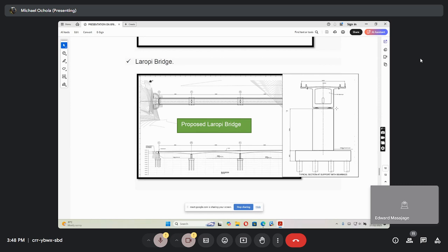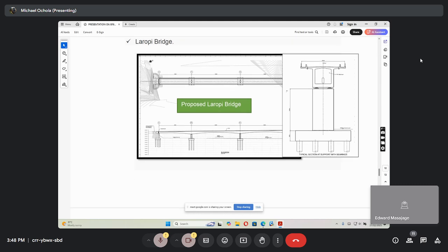That point, yeah, it is only the support down here. So any lateral force here is transferred and creates an effect on the pile cap and pile and the bottom of this pier at this point. So you concentrate your checks and design more around here. Very important.